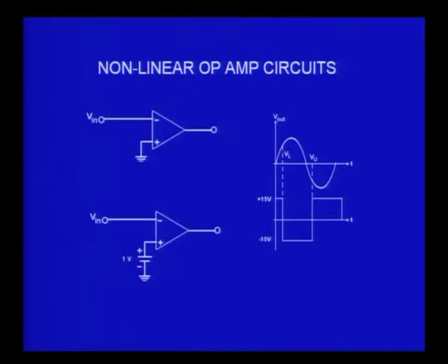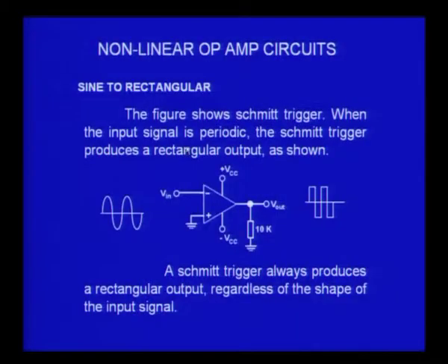So, if it is 1 volt, when the other voltage exceeds the 1 volt by plus or minus 140 microvolts, then you will get an output which is a square wave. So, you can see therefore that you can also provide an additional bias or a level to the comparison of the two voltages. That is exactly what I have shown in the next slide.